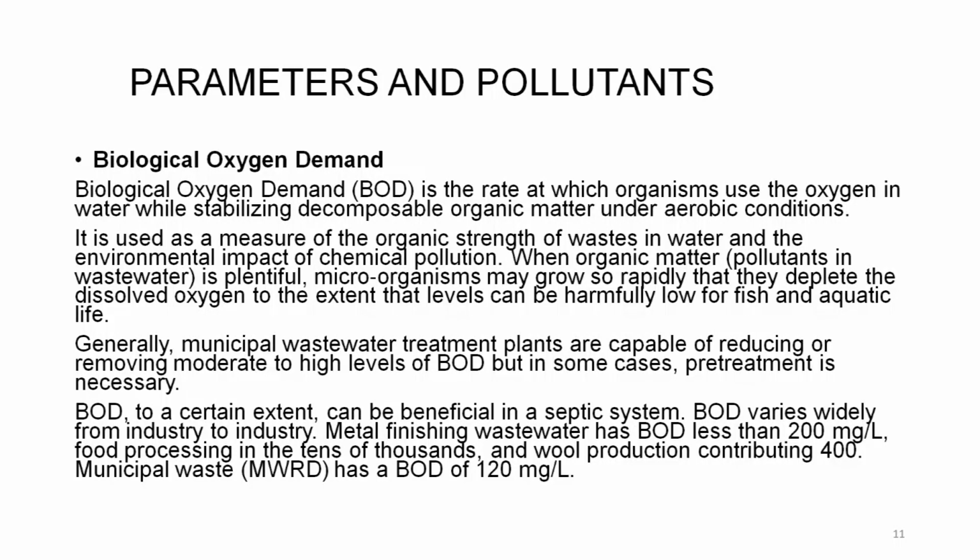Generally, municipal wastewater treatment plants are capable of reducing or removing moderate to high levels of BOD, but in some cases pre-treatment is necessary. BOD to a certain extent can be beneficial in a septic system. BOD varies widely from industry to industry.